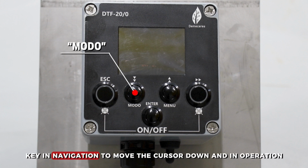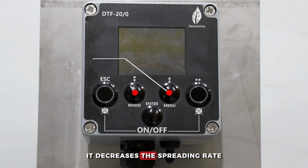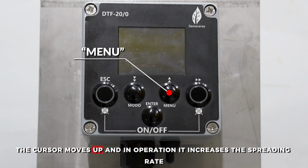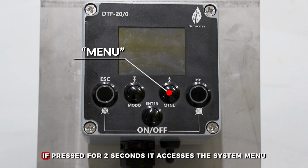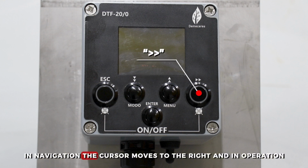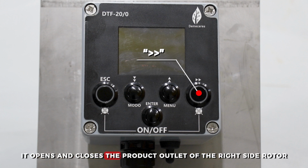Key in navigation to move the cursor down, and in operation, it decreases the spreading rate. In navigation, the cursor moves up, and in operation, it increases the spreading rate. If pressed for 2 seconds, it accesses the system menu. In navigation, the cursor moves to the right, and in operation, it opens and closes the product outlet of the right side rotor.